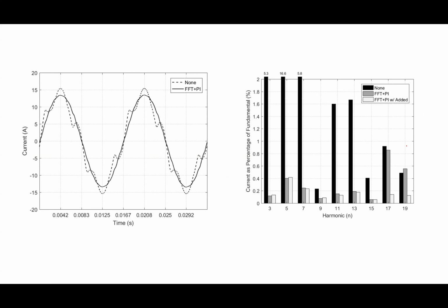Some of you actually used it and showed it to me on the project, whether you realize it or not. So that's an FFT. That's a Fourier transform. We're going to learn a little bit about the Fourier transform. First thing I'm talking about is the Fourier series, which is the basic concept, and then I take it to the Fourier transform. The Fourier transform basically tells me at what frequencies I have information in that signal and how much. So the height of those things tells me how much information.